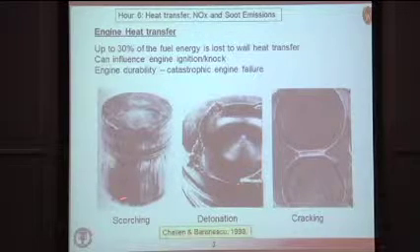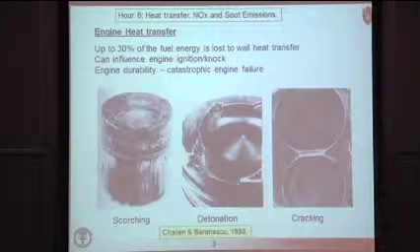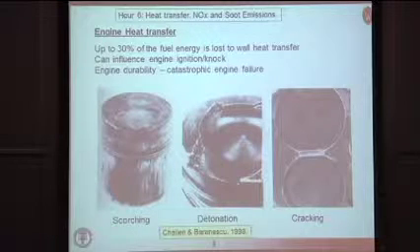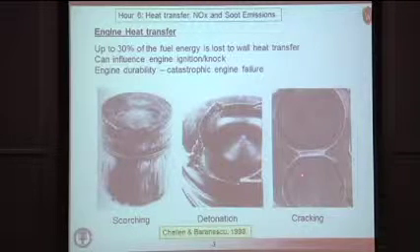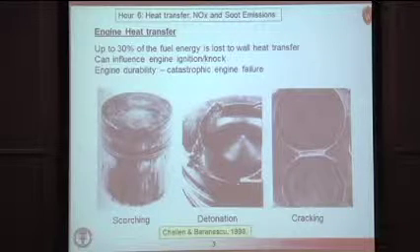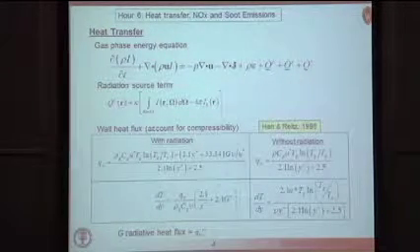Here are some examples of things that can happen. This actually happened in our engine here, where you have cracks appearing between the intake valves, due to high temperature in the chamber causing differential expansion in that thin area, leading to potentially major damage in an engine.